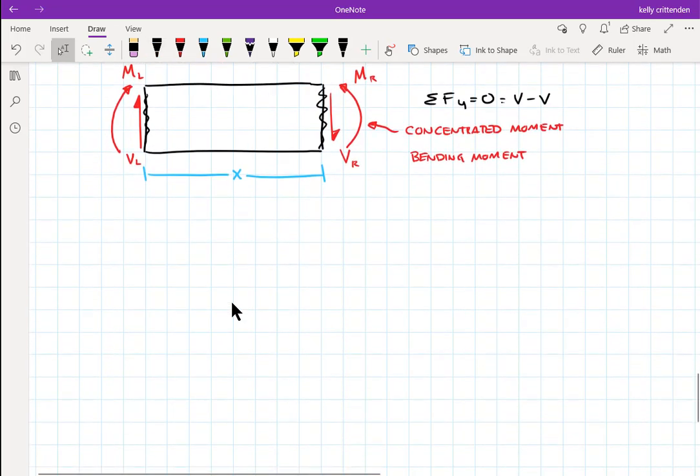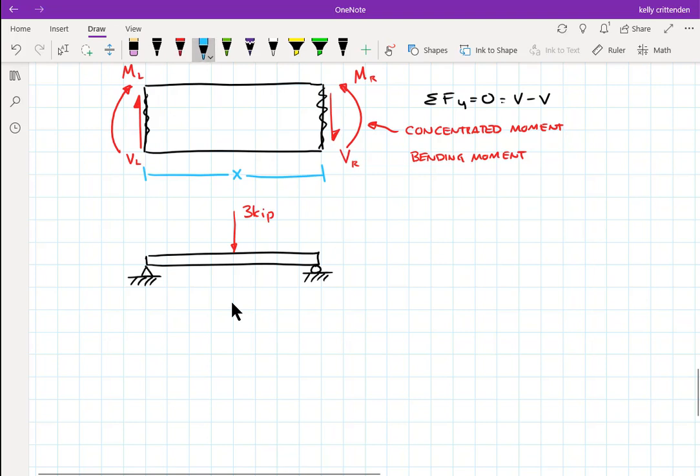Actually, this next thing might help it make some sense because we're going to put numbers on it. Let's just do a pretty simple one. We've been drawing this beam that has a pin and a roller, so let's keep with that. Remember, this is simply supported, but let's put numbers on it. Let's say that this is 3 kips, so 3,000 pounds, and let's make this 4 feet. I don't want it to be centered, so let's make this 3 feet, even though it doesn't look like that, just so it's not centered. Sometimes people have problems with stuff being centered.